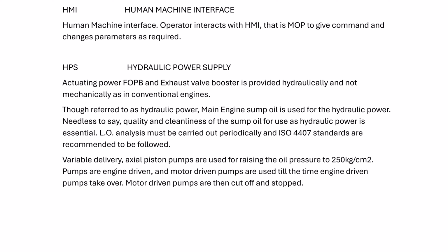System oil is drawn by the lube oil pump as normal. One part goes to lubrication, as in a conventional engine, to the bearings and piston cooling, etc. The other part goes to the control system as hydraulic oil. That part has to be maintained clean.